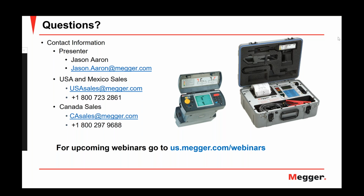So you want to set the voltage properly, and that's why part of the verification that you do every time you go to check the battery or do the inspections is to check the float voltages. As part of the results, the form shows you the total voltage, and you can compare that to what it should be, and if it's not like that, then you should take action. There are many other things to consider, but temperature and float voltages are the ones that I would recommend initially to take care of.